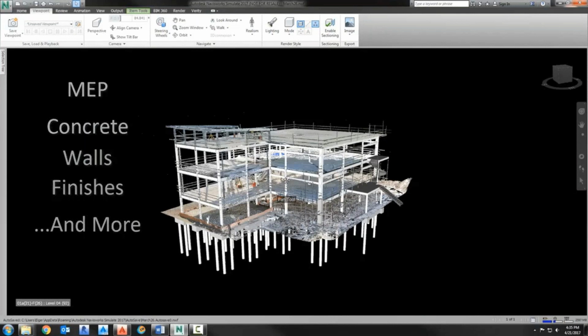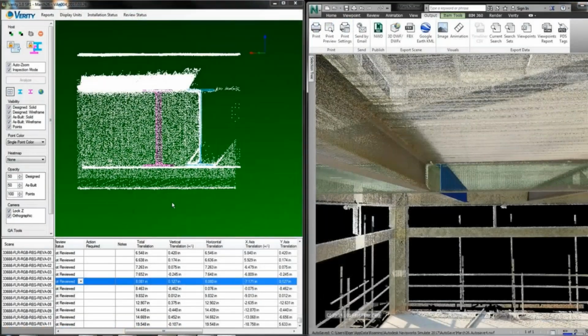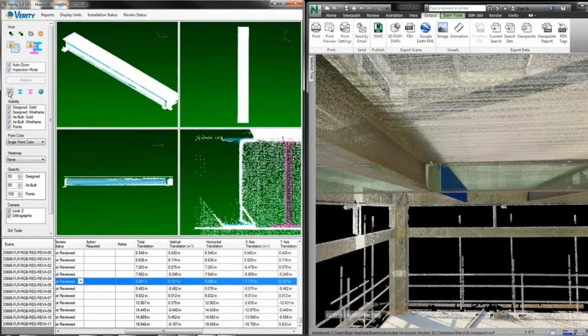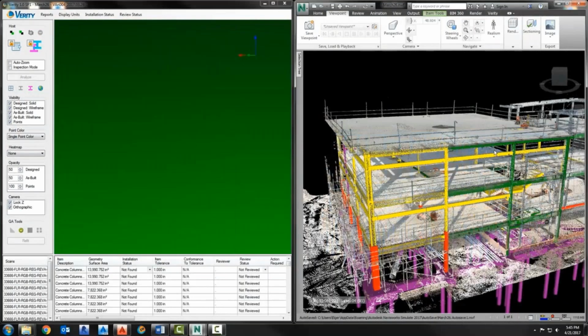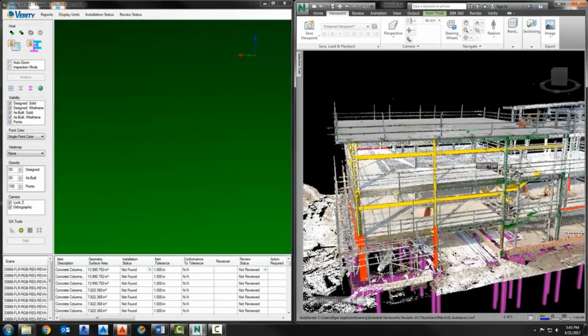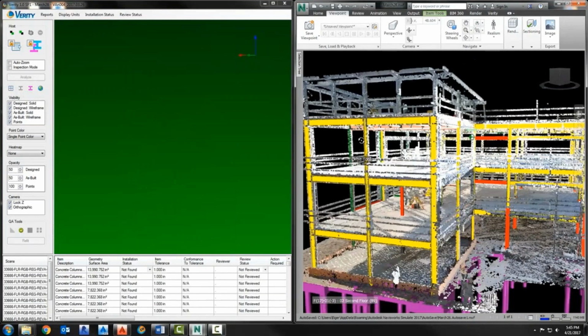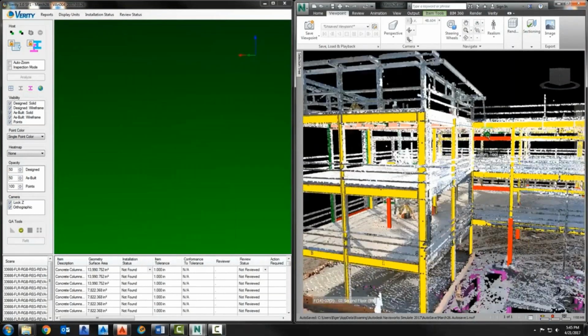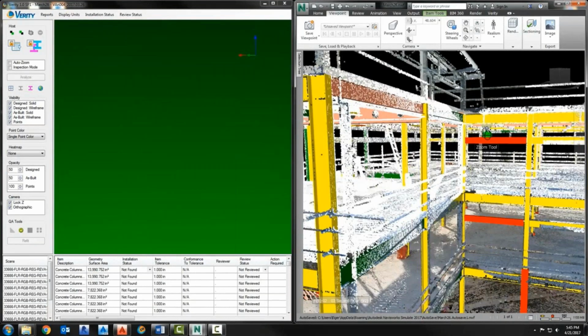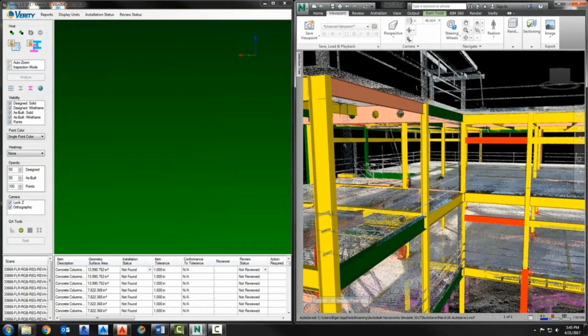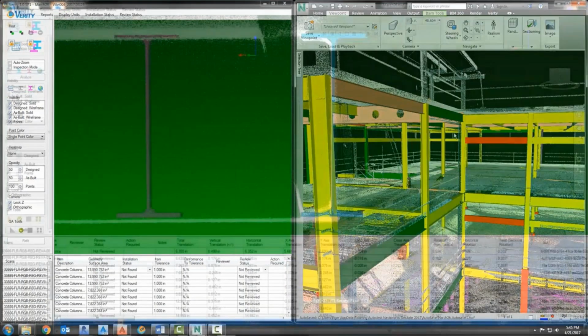And you will see now on your left-hand side, you can see the discrepancy between the as-built properties versus the model. You can see that the I sections are spaced out. And if you toggle on the right-hand side, it has a full push functionality to Navisworks. And what it does is it color codes the beams or structures by tolerances, so yellow, green, and red.